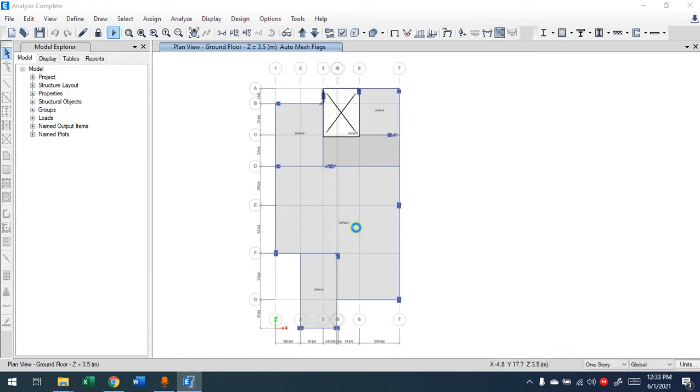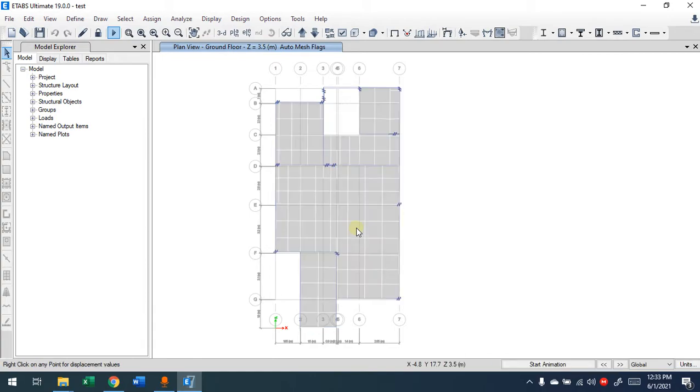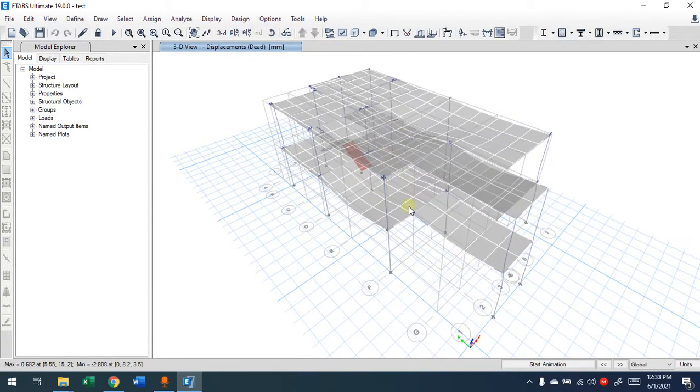It's more appropriate for the cases when you have irregular slabs, because in irregular slabs, Etabs knows better where the meshing size should be. Look, the meshing here is like this. So this is what a rectangular mesh will look like. It assumes that the deflection will happen on this line here, because those lines will be assumed as joint rotation deflections in the analysis. If you leave it for general, so I'm deleting this one.